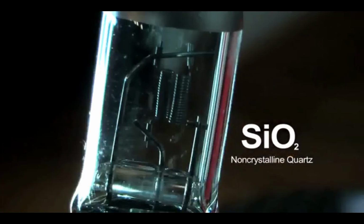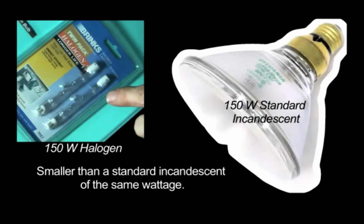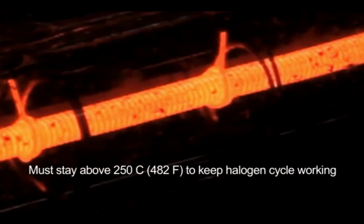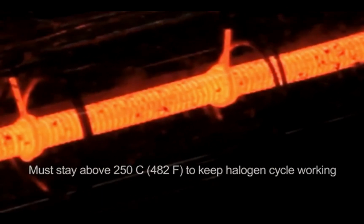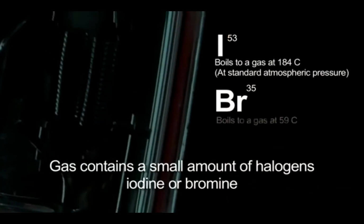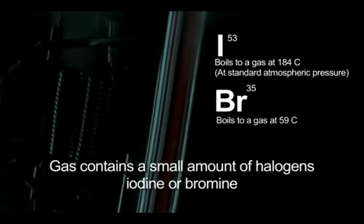light. The difference with halogen is, number one, the outer envelope is made out of quartz instead of glass, and it's much smaller for the same wattage, and that's one reason for quartz, to withstand the higher heat because of the smaller bulb. Secondly, the bulb is filled with a halogen gas, which is unique in that it causes what's known as the halogen regenerative cycle.